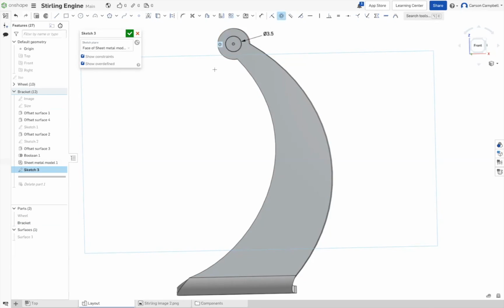How come that's cyan? Because it's outside the sketch, it's the edge. And will it scale with this guy now? It won't scale with it because your dimension is a solid. Delete 3.5. Dimension the diameter of the circle to that edge. Dimension that to that and place it. And hit enter, if that's your design intent.